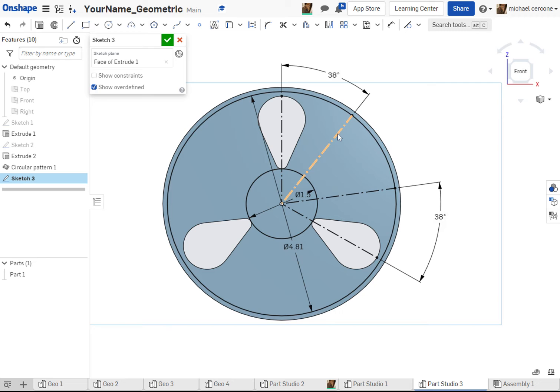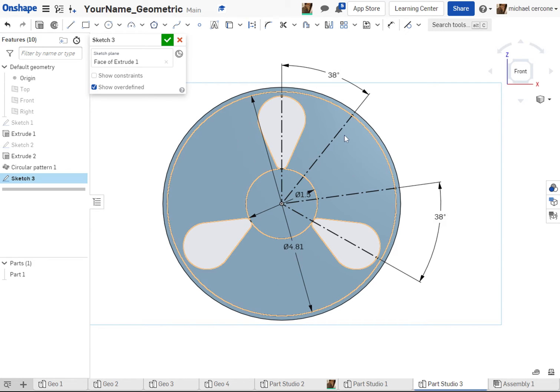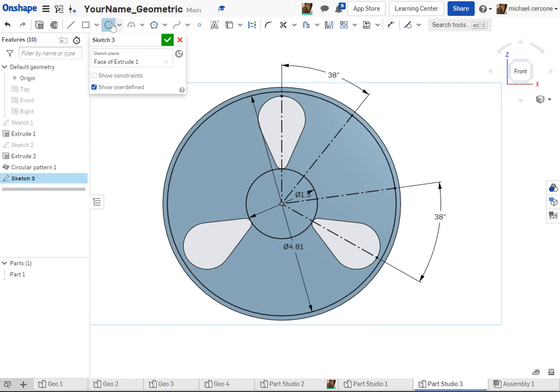And now I need to figure out where the center is. I now have this point here, but I don't know where the center of that 3/4 radius is. But I do have another construction circle. It was one that we drew over here for the 3 5/8. So I'm actually just going to snap this one. Doesn't want to bring up that center mark, so I'll just draw it and type in 3 plus 5 divided by 8.